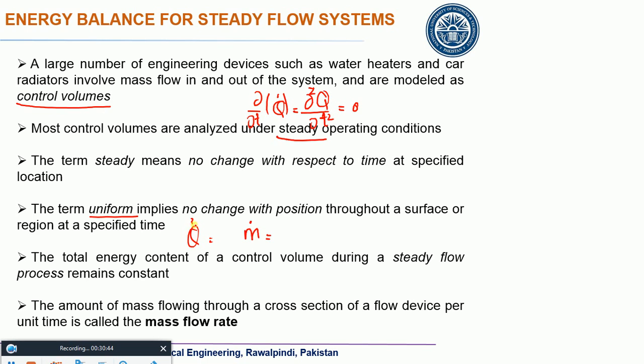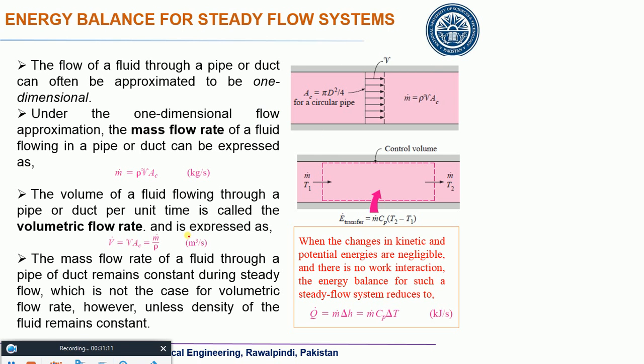So that Q dot, I am talking about the volumetric flow rate. So that Q dot is equal to what? A V. So you can connect it with this m dot. You can always multiply it with rho and get m dot, isn't it? So this is the mass flow rate. You know what is it? Cross sectional area multiply velocity. You should know this term, right? Previous semester.